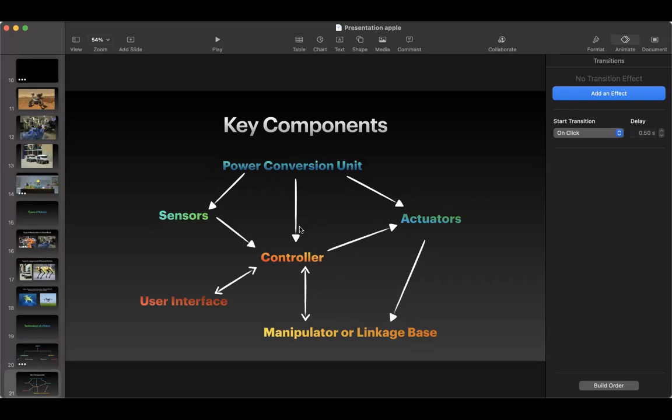If it is so close at a point, now the sensor is giving, now this is very close. The sensor is actually not saying whether it's close or there is more to go, right? The sensor is just giving you distance. First it was 30 and now the sensor is saying there are only 10 centimeters to the wall. So now the controller identifies, okay, now we are too close to the wall. If you go forward, then we will knock on the wall, right? So therefore the controller is deciding, okay, 30 centimeters is okay, but 10 centimeters is not okay.